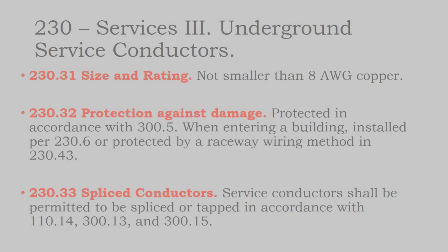Number 6 and number 8 copper are pretty thick, and you put a crimp around the two pieces of bare copper, and then you press this thing together as hard as you can and permanently crimp them together. It's not nearly as good as using a continuous run of copper, but it's considered to be continuous. Putting an acorn to connect your bare copper to your ground rod will require protection. So, conductors need to be protected.